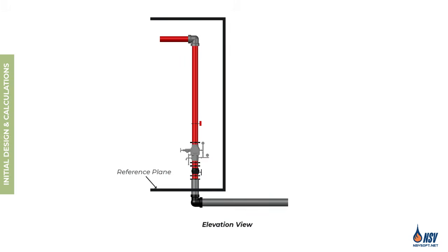We also assume that the elevation of the BOR node is 1 foot above the floor level. Finally, because the flow test is performed through the outlet of a fire hydrant without digging into the ground, we assume the test node is 2 feet above grade.